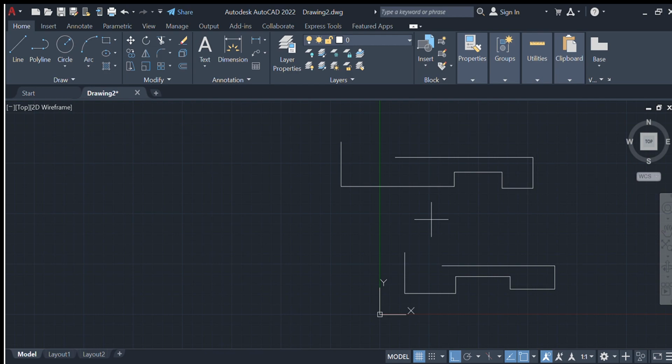All you need to do, once you click on your line or your polyline, is specify the point you want to start from. So how do you do that? Your cursor is currently on your x-axis, so just input, let me see, 13 on your x-axis, and press Tab on your computer. It will move to the y-axis, then input 23 there and press Enter.